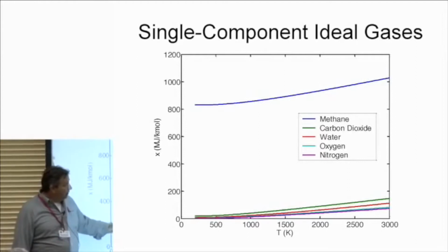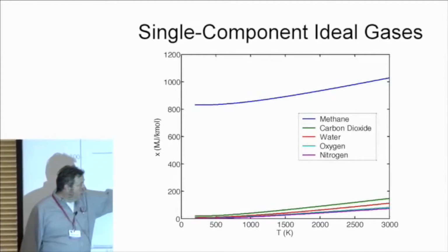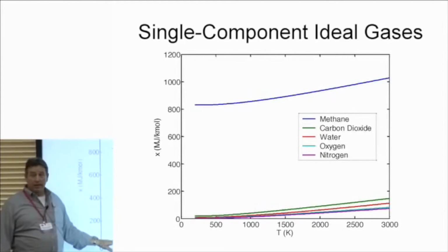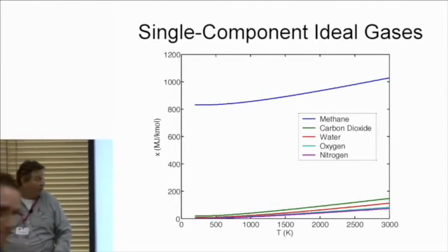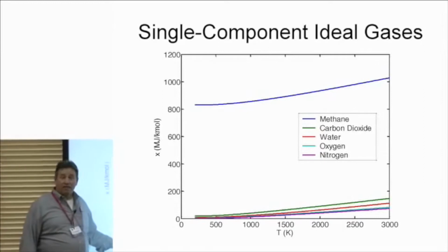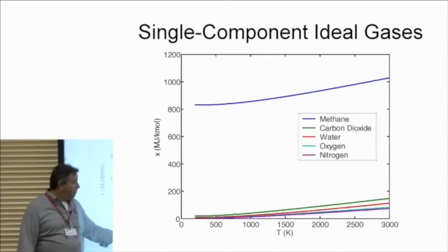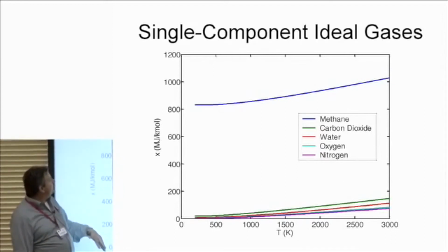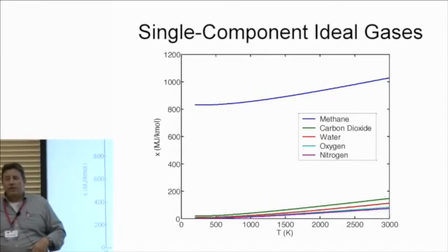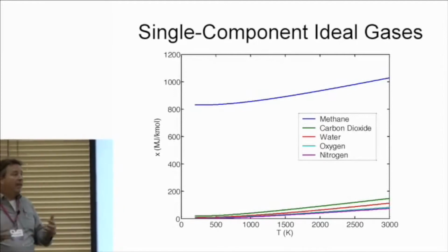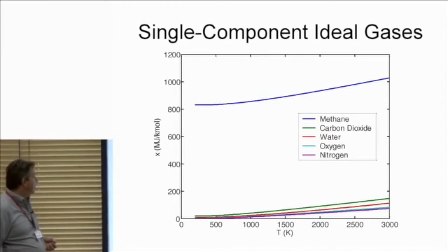If we look at the various products, so these are pure, so CO2, water, oxygen, in the atmosphere, but the atmosphere has lots of nitrogen, so nitrogen, not very valuable. Water, more valuable. So it all depends on how much I have. And then if I raise the temperature and the pressure, this is all at atmospheric pressure, then they become more valuable. I pump up that thermomechanical component of the exergy.